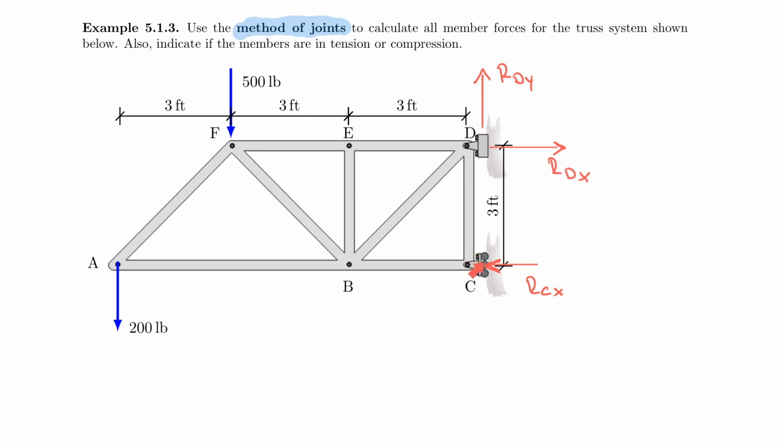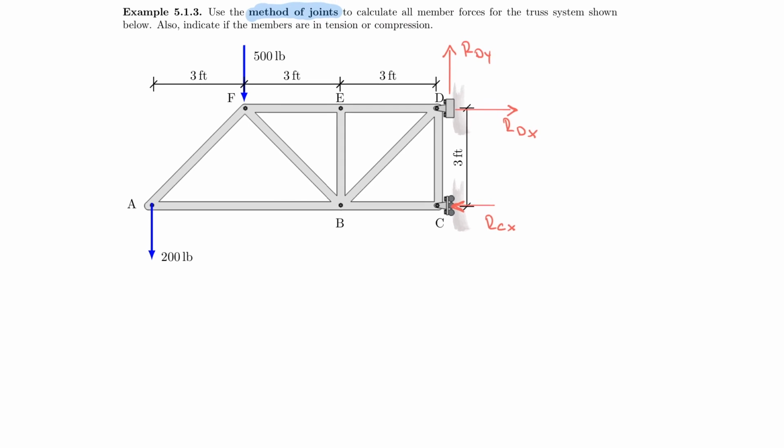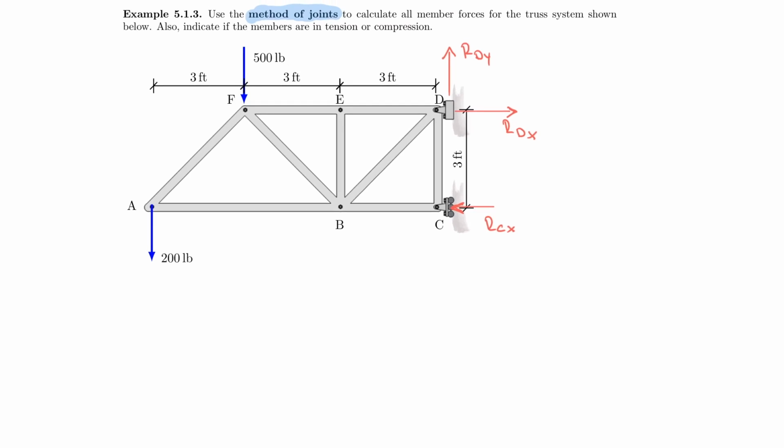And remember from our internal forces for rigid bodies that we always could work our way in towards the cantilever without even calculating the support reaction. So this is kind of similar here. I can work my way from here all the way into the system. And then I can use my support reactions to actually understand if my answers are correct or not. So let's do that. Let us actually start by cutting the system at node A. So cut node A.